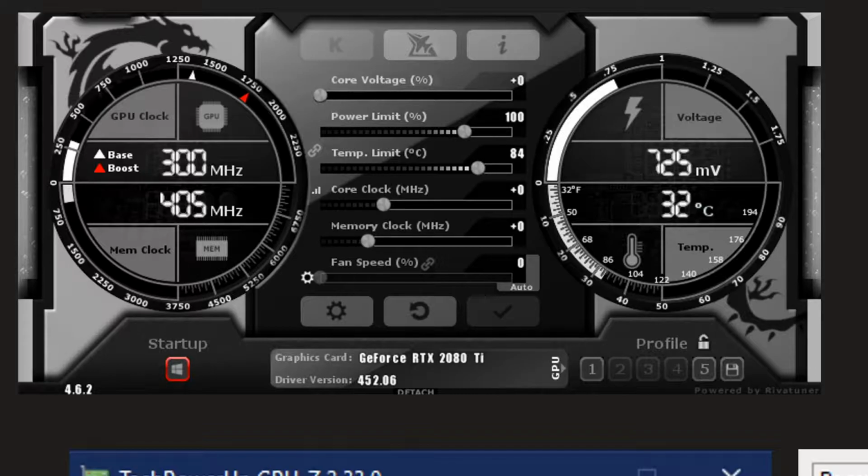So I would still say to max the power limit, because technically the card should be designed for that. Unless it's an Asus card, because my RX 570 Expedition, well, that one blew up. Even though that probably was a faulty MOSFET. I would still say it's 99.9% safe to just max the power limit on AMD. Maybe you should look into what VRM your card is running and then determine for yourself if the VRM can take the extra power.